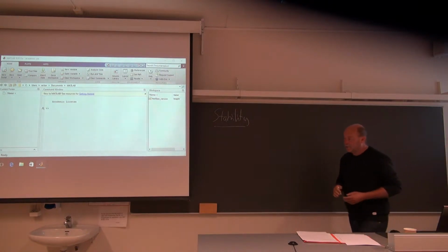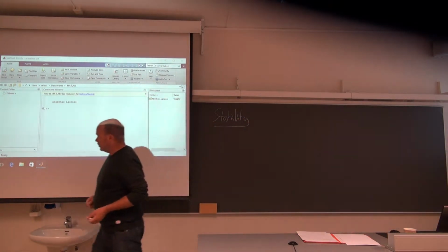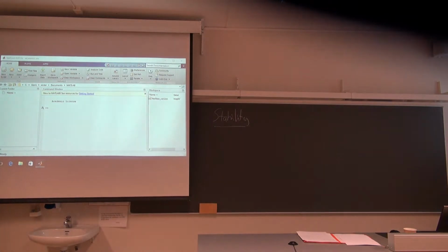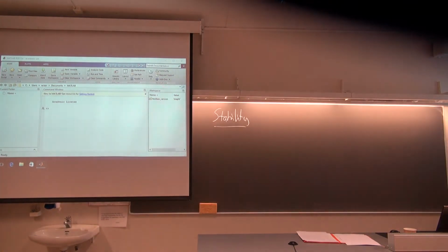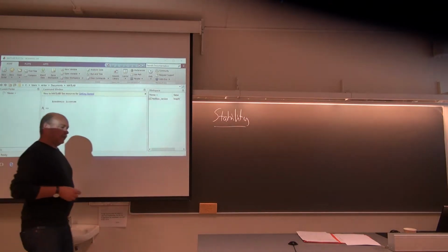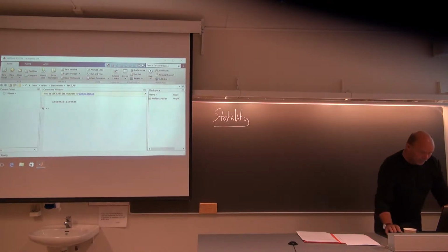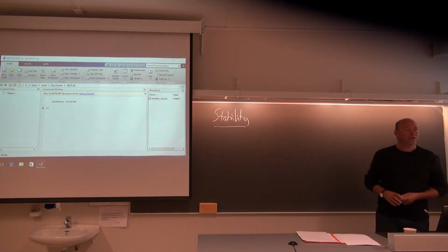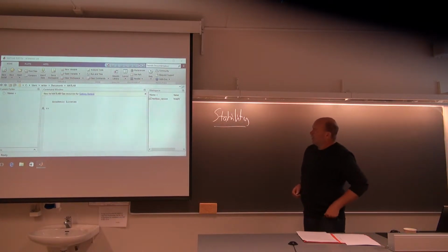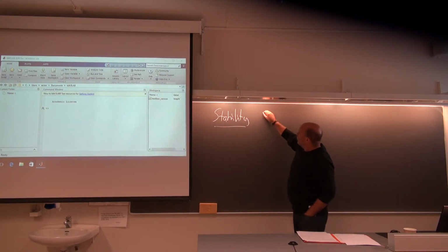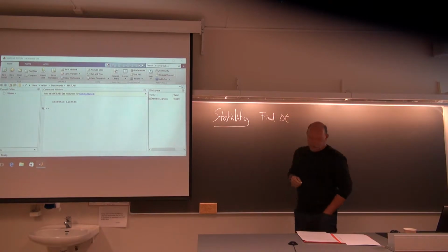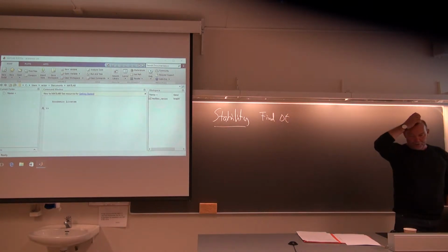We have to find a delta t, which is as big as possible without the code actually exploding. We want to have a good solution quite accurately, but we don't want to spend days or months simulating, so we need to find a good delta t. So that's our aim here.